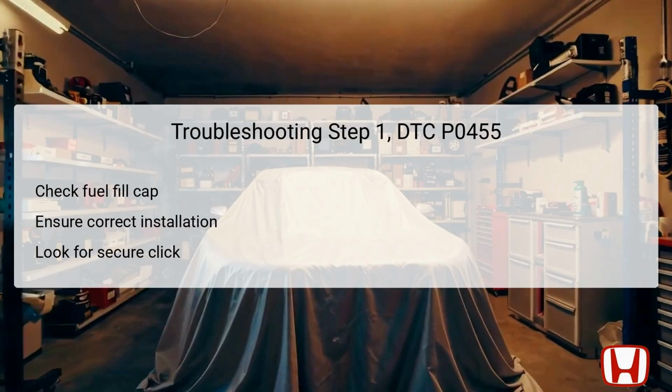The first step in troubleshooting DTC P0455 involves checking the fuel fill cap. This is a critical component as it seals the fuel tank from the atmosphere. Ensure that the cap is the correct one for the vehicle and that it is installed properly. The fuel fill cap should have markings indicating tighten to click, and it must turn a quarter turn after being tightened to ensure it's secure.